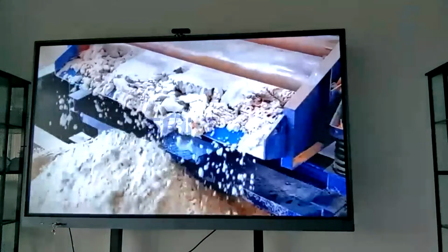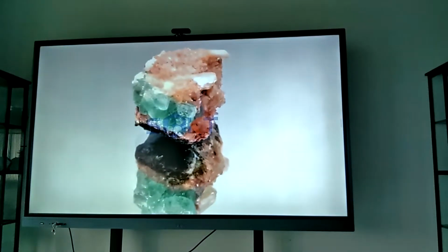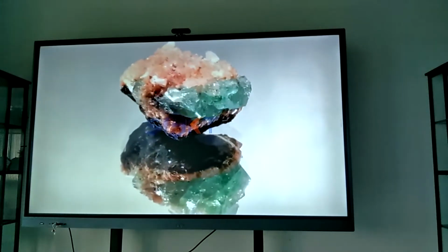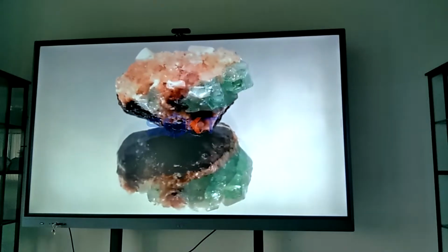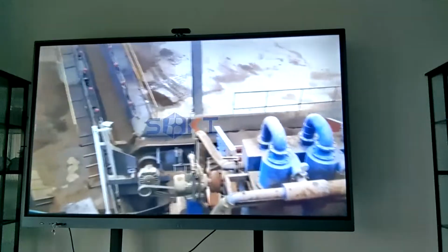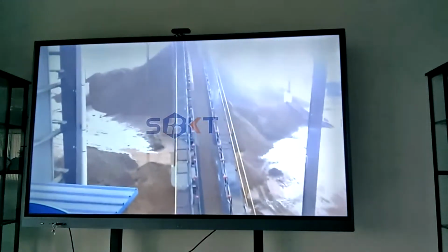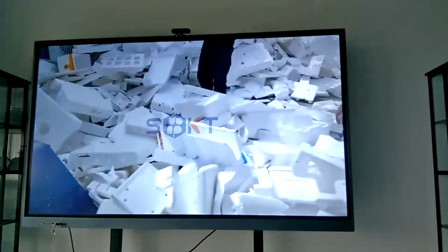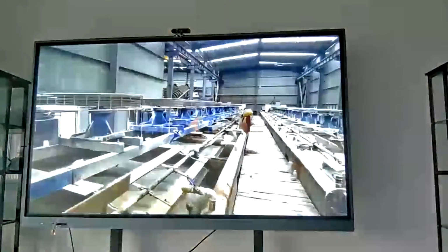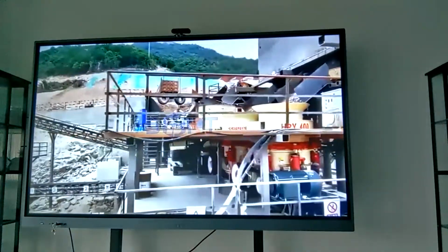Five is the refractory gold or encased gold, high arsenic, high sulfur treatment, and cyanidation characteristics. Gold is encased in pyrite, arsenic associated with organic carbon. Gold leaching directly, the leaching rate is extremely low.